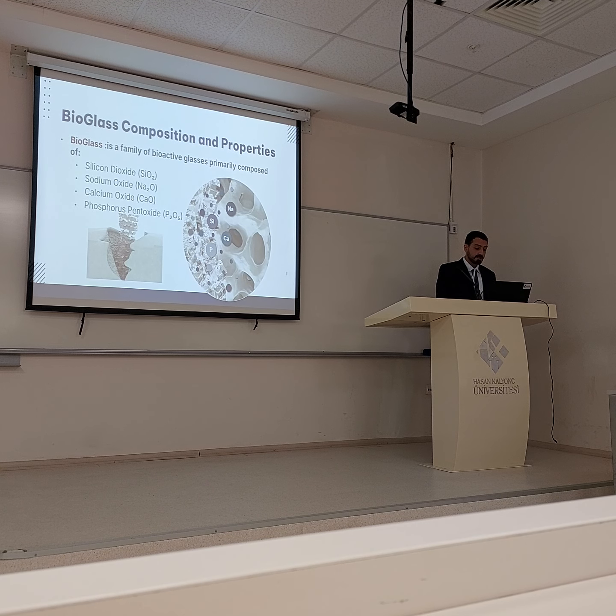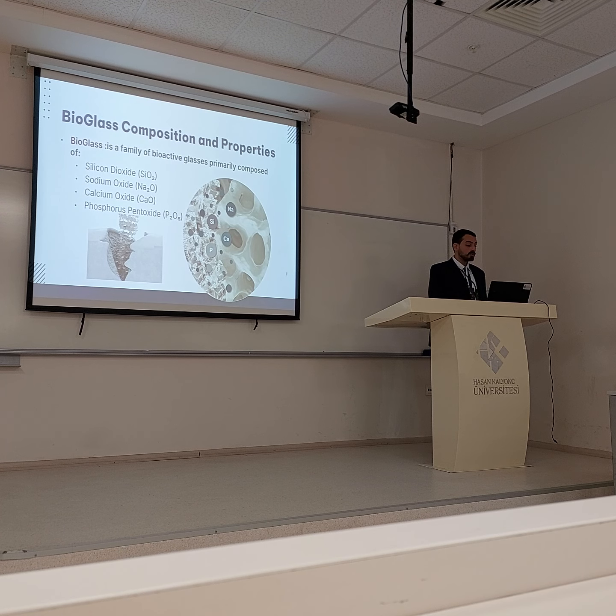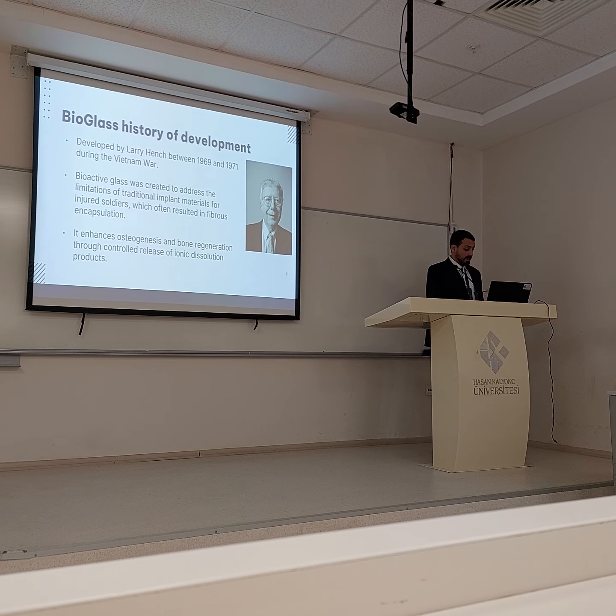Simply, what's bioglass? Generally, when you think about bioglass, you think about a glass. But really, yes, it's a glass, but normally used inside the body, used inside the bones. But it's called glass because it contains a lot of silicon dioxide. So bioglass is a family of bioactive glasses, primarily composed of silicon dioxide, sodium oxide, calcium oxide, and phosphorus pentoxide. Created by Larry Hench in the Vietnam War.